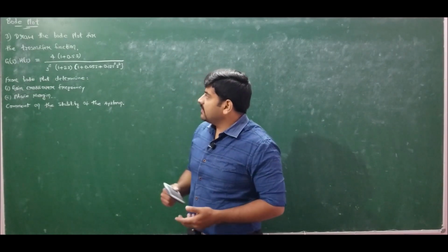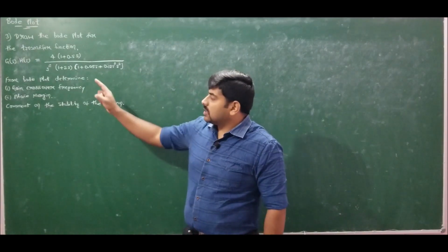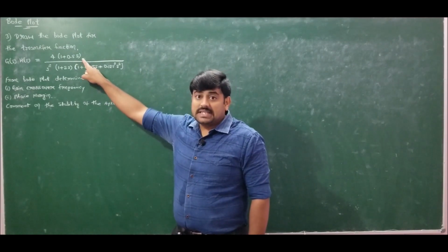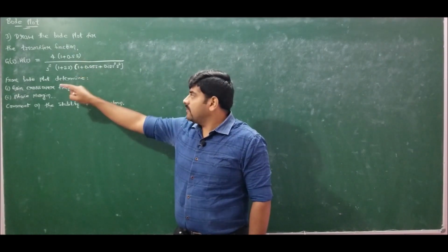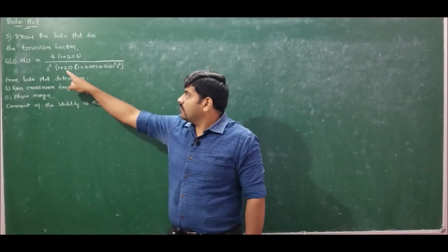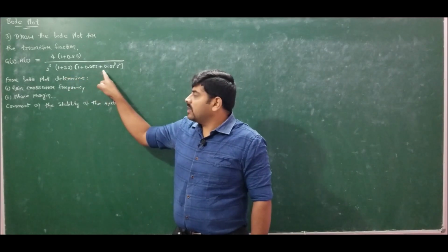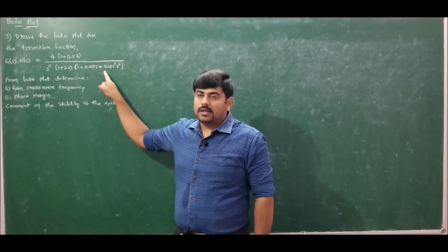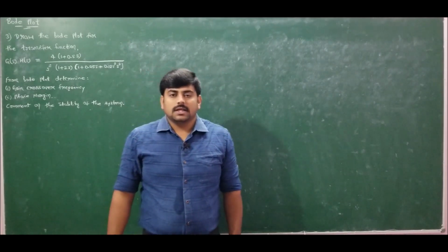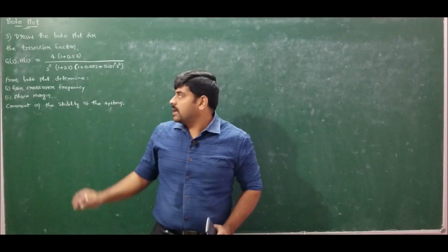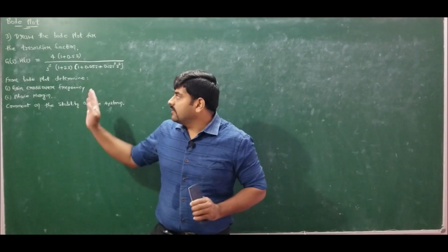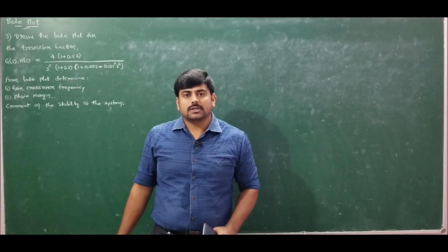If we observe the given transfer function, it has a constant K whose value is 4, and we have one simple zero because it is in the numerator, and we have an s square term, that is 2 poles at origin, and we have one simple pole and we have one complex pole. Come, let us solve this problem. The given problem itself is in standard time constant form, so no need to worry about converting the given transfer function to standard time constant form.